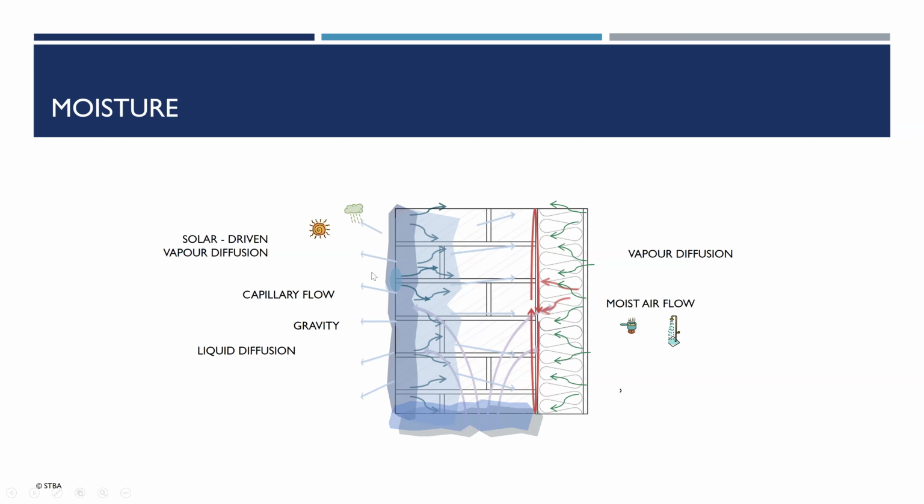Some of that water, which is absorbed into the masonry, will evaporate to the outside, but depending on context, some of it can be driven further into the wall, and on occasion it can go all the way through to the insulation. So if you have an impermeable insulation layer on the inside, that has nowhere to go, and that's potentially bad news. So you need a moisture risk assessment that looks at all of this.